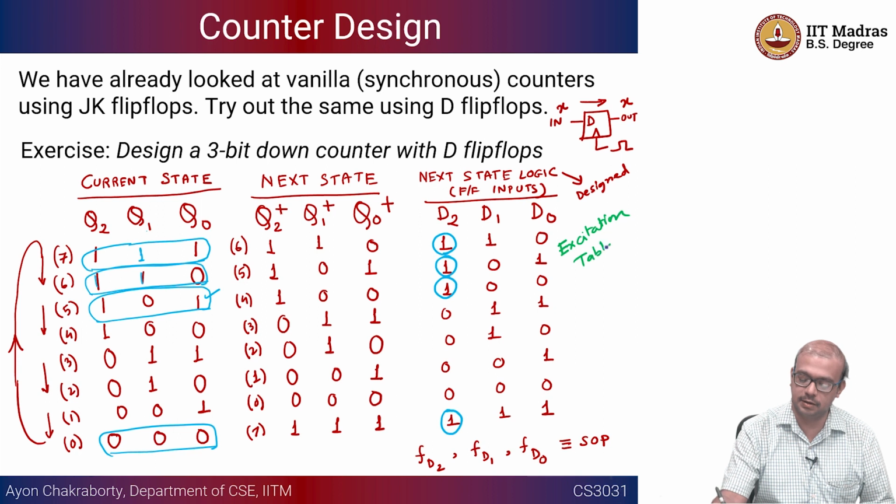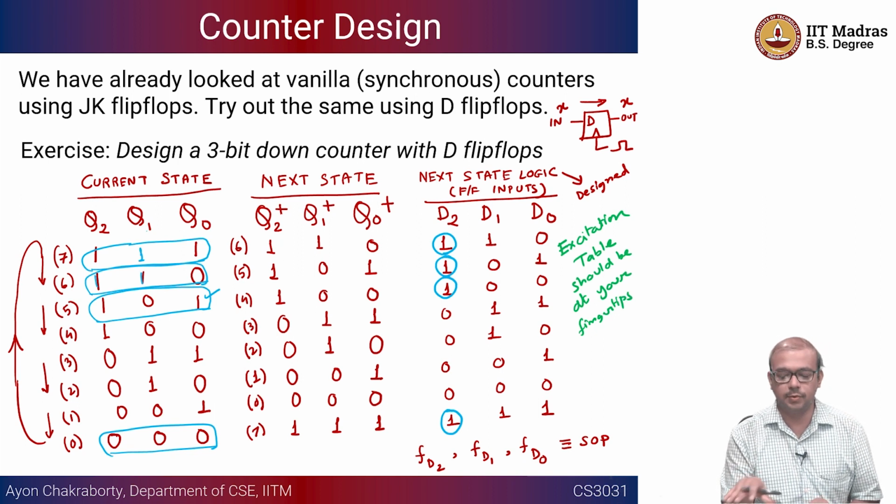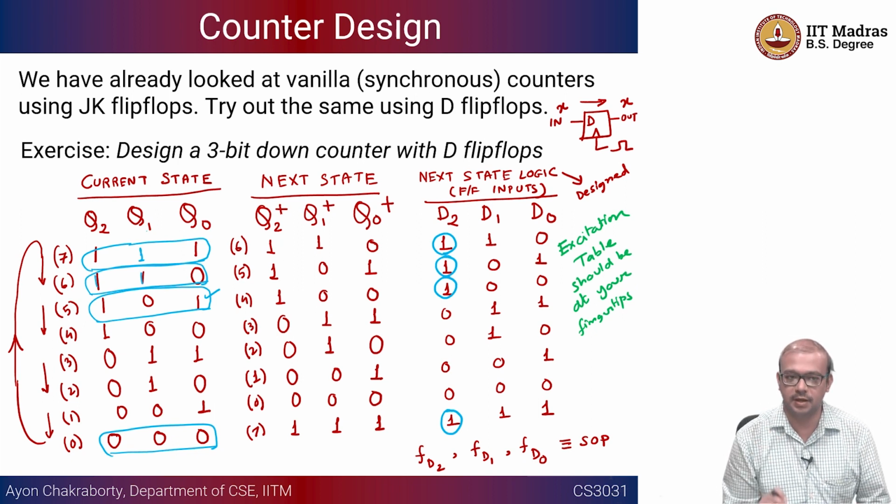Excitation table should be at your fingertips. Okay, so without the excitation table you cannot find out these particular inputs, because the excitation table is a more primitive table that has been derived from the architecture of the flip-flop, right?